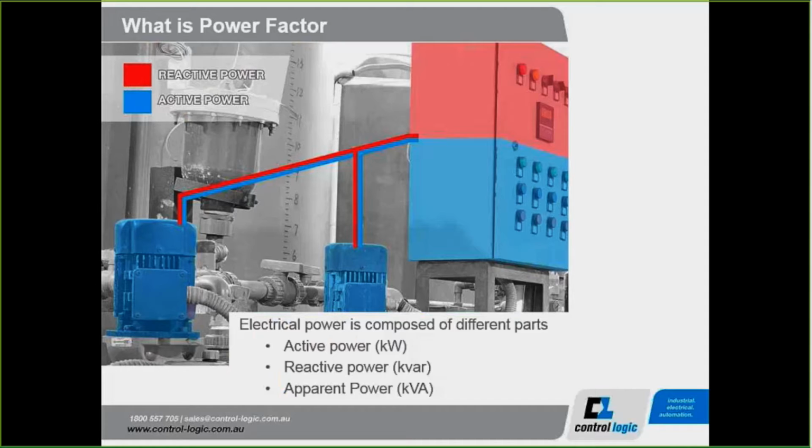Now, devices such as induction motors invariably consume reactive power. They need this power to create the magnetic fields in their windings for the motor to function correctly. So reactive power is always part of an induction motor; it's required to correctly magnetise it so it can operate correctly.